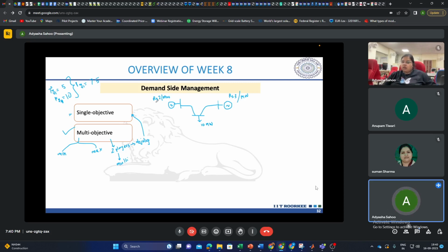But in combination with the cost function, we also need to take into account the losses in the system. The losses in turn depend upon the line resistance here, right? The resistance of these lines. So let's say you are generating 10 megawatt of power here, but these are extremely lossy lines. So let's say 2 megawatt of power is lost here. So finally what you get here is 8 megawatt of power. But again here, even if it is costly, if it is connected to a line which is less lossy, and you inject your 10 megawatt of power, maybe you will get 9.5. So how to strike a balance between this cost minimization and loss minimization?